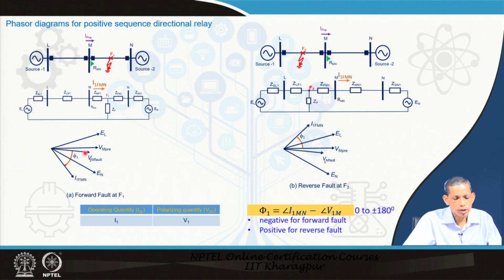So, now the corresponding V fault at that bus decreases. So, this is decrement. Now, we compute from this V A, V B, V C the corresponding V1M fault, positive sequence at fault. Note that when we are computing the V1M fault, V A, V B, V C will be available, and we orient V B and V C towards A phase, that is 1/3 of (1 plus alpha V B plus alpha square V C). So, that results in your positive sequence voltage.